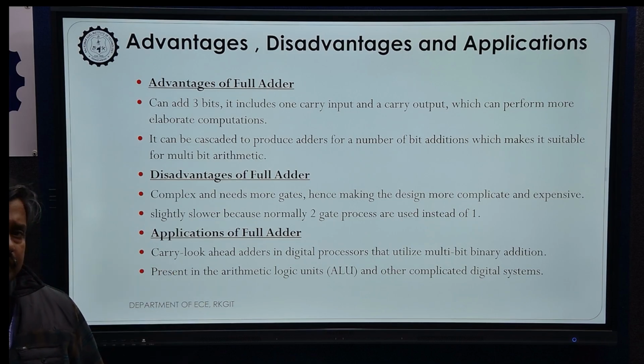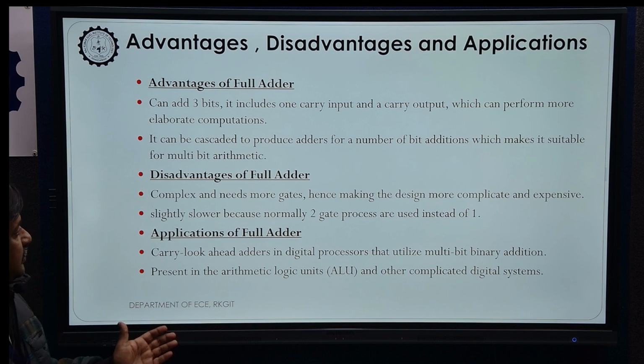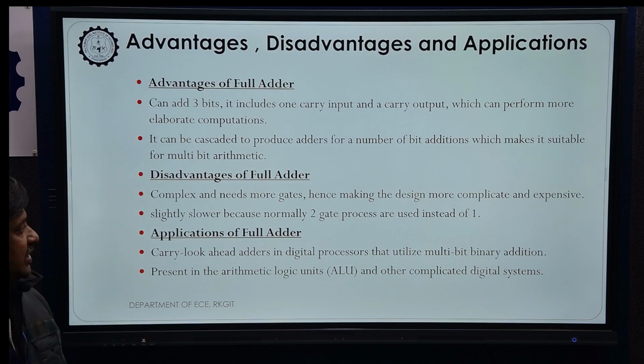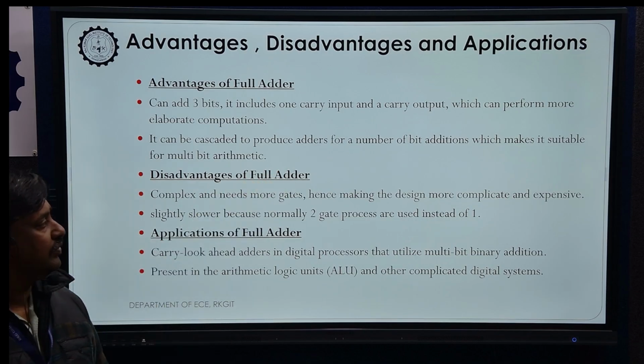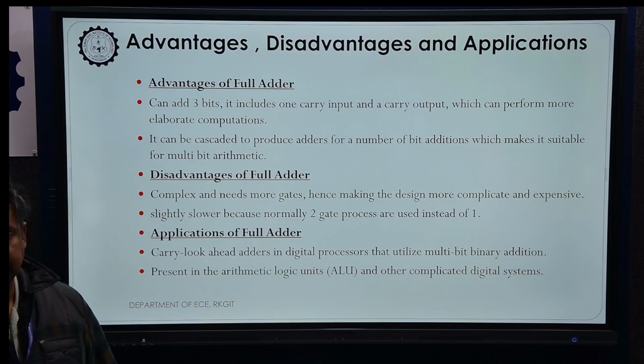In the case of the half adder we don't have the carry input calculation, but here we have the carry input also. So when we go for multi-bit addition, the full adder will be useful. It can be cascaded to produce adders for multi-bit addition, which makes it suitable for parallel adders and different types of adders which use full adders because of the provision of carry input.